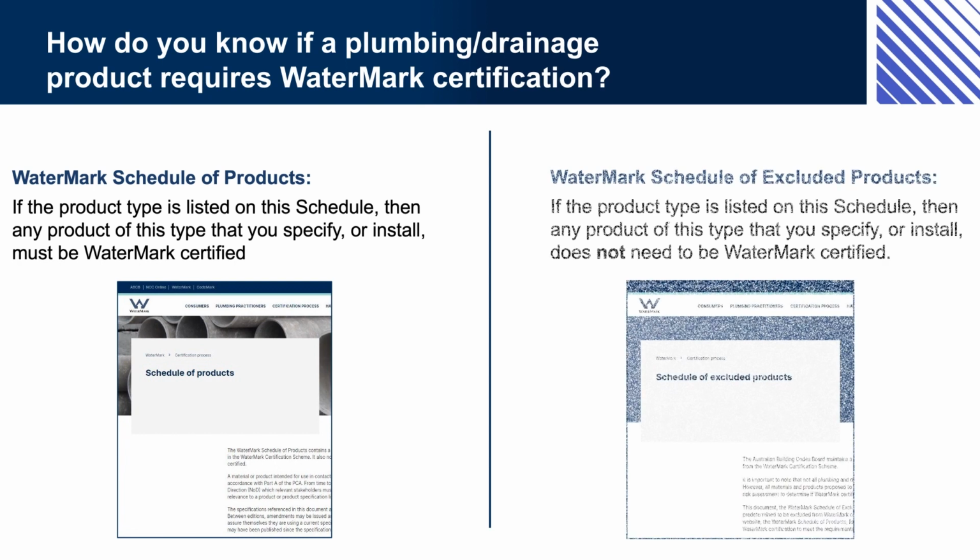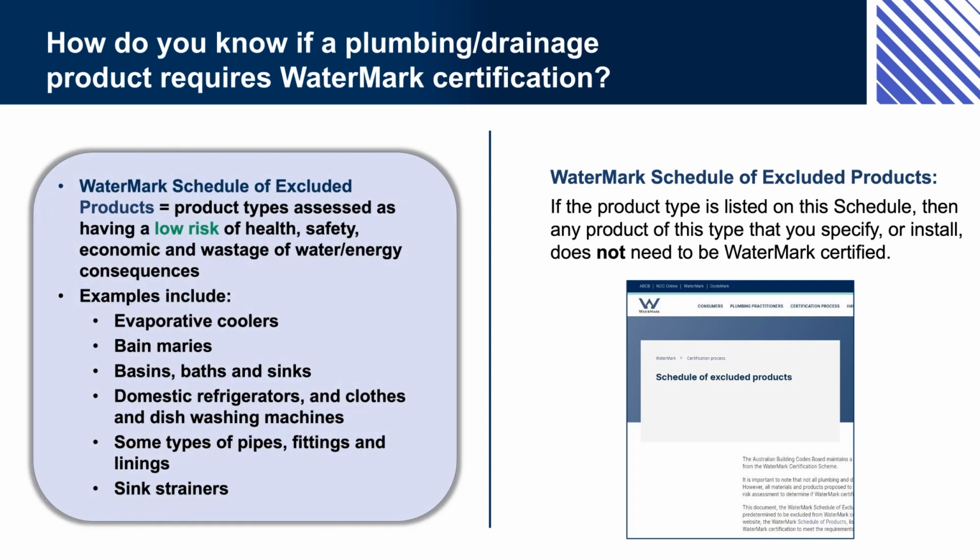Similarly, if you are specifying or installing a new bain-marie in a cafe, you need to check these schedules to find out if bain-maries need to be WaterMark certified. They are listed in the Schedule of Excluded Products, so you wouldn't have to get a WaterMark certified product in this case. Note that this doesn't mean that the bain-marie doesn't have to meet any standards at all. Other regulations may apply to it, and an approving authority might want to see evidence of suitability before they approve the installation.